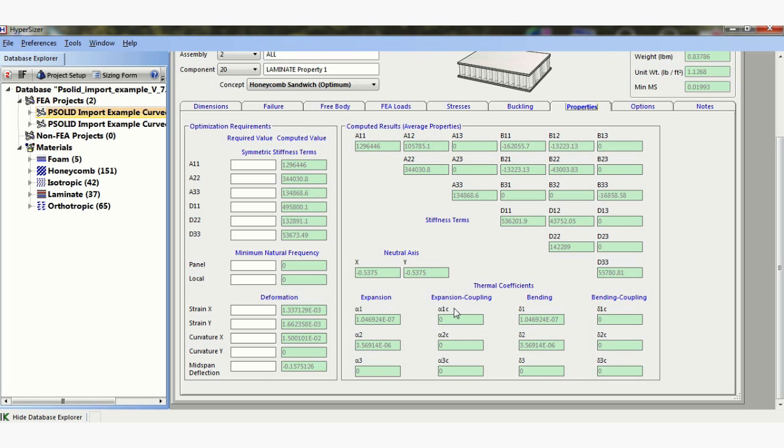again, I think thermal should be separate. Why not have a thermal tab? Hey, let's have a thermal tab. Tell me what's going on with this thermal stuff. I want to separate it from my mechanical loads. Good stress engineers always separate your thermal loads from mechanical loads.